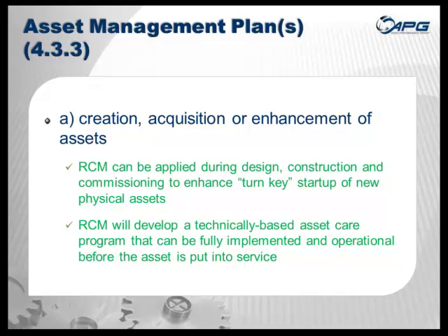In fact, looking into RCM origins, if you will, its real origins in the Nolan and Heap era were during that design and construction and commissioning of new aircraft. In general industry, we tend to find the RCM work identification strategies applied on existing assets. So it does apply to both, but it is absolutely applicable during that creation, acquisition, and enhancement phase. And when done this way, RCM will develop a technically based asset care program that can be implemented and operational before the asset is put into service, and then the benefits can be realized literally at start.